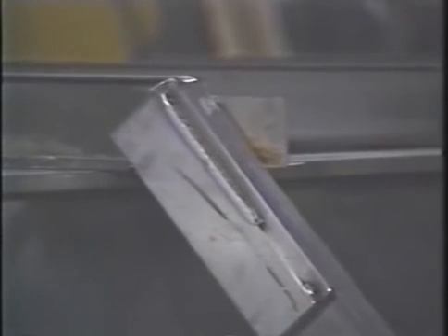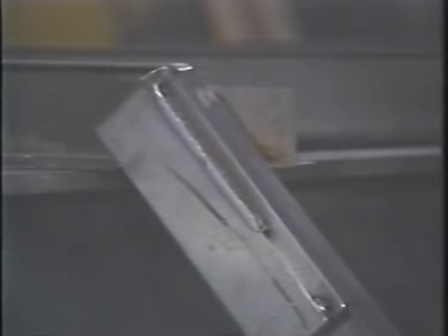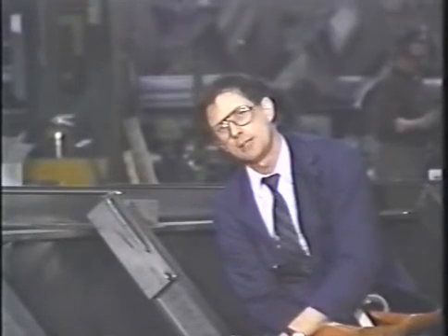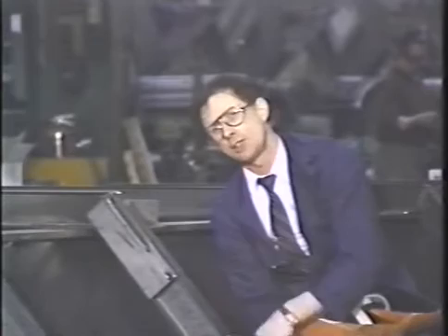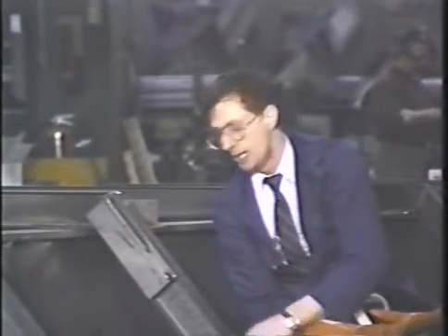When you're welding on an application such as this, where it's just over 1/8 of an inch, and you want to put a nice bead without spatter, you obviously need more heat. Using now 75 or 80% argon and 20% CO2 is fine for an application like this.